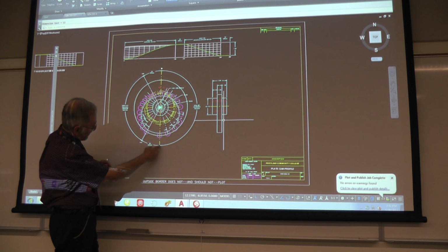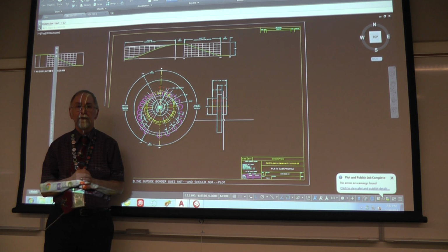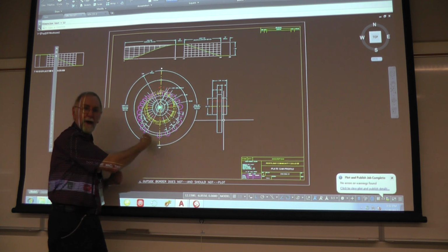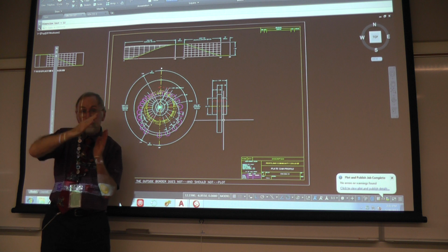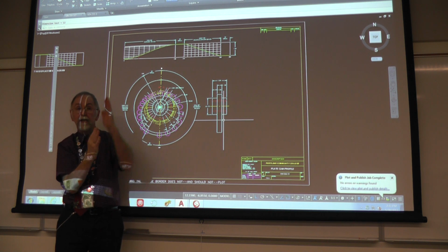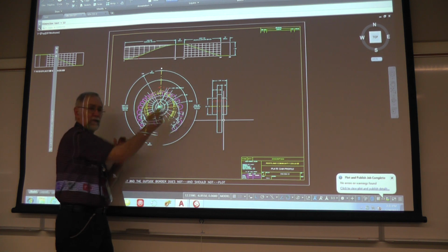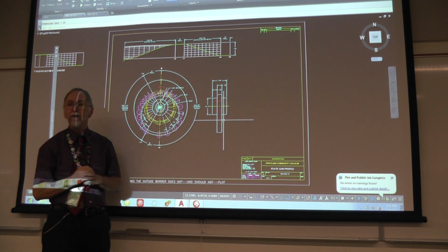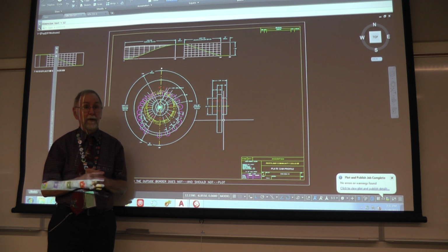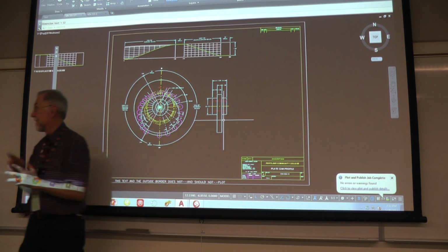But then when you go over to here, it might show up that it's 31 degrees. So once you get this dimension on here, rotate this back however much you went over. If you went over a quarter of a degree, come back a quarter of a degree, it's now parallel, but you've got this dimension in here, and then this one will actually come out. It's not cheating, it's just, you know, taking my lemons and making some lemonade out of it. It's just AutoCAD.